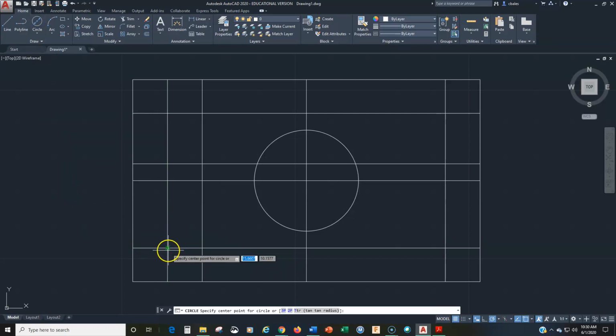And look now, since there's no midpoint here, that's why the intersection comes up. And there we go. As soon as that symbol comes up, then I can click, right? So I don't have to physically go in there, although it's pretty hard not to. We go in there and we click and we type in 0.5 for the 0.5 circle.